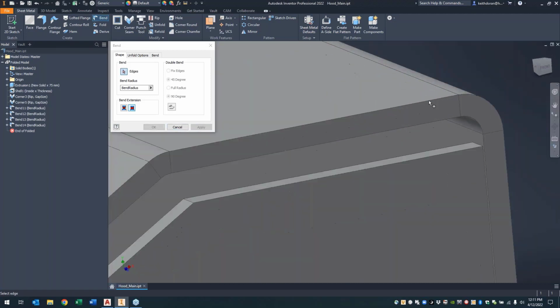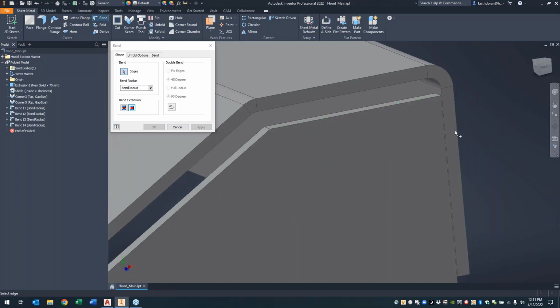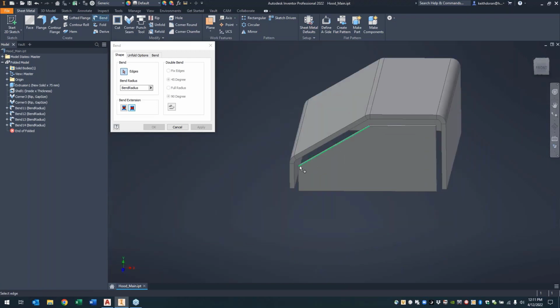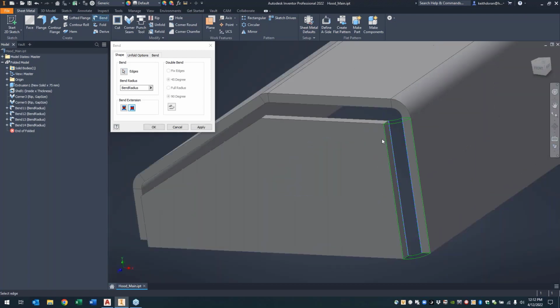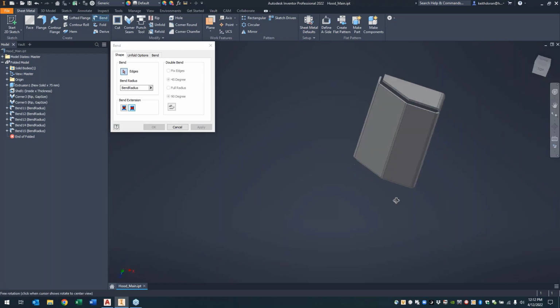Okay. So it was freaking out because it didn't know what to do with this upper corner. It was sharp. That was not an actual bent corner. So I was skipping a key step of this, which in this case is, we know we have bent flanges on this upper area, so making sure to select those first to get them done. So the gist of this is if you have a component like this, you want to rip away all the boundaries you don't need, apply the bends where the bends exist as solid objects, in this case the flanges, and then go back in and create the bends where you have potential gaps that you want to close back up.